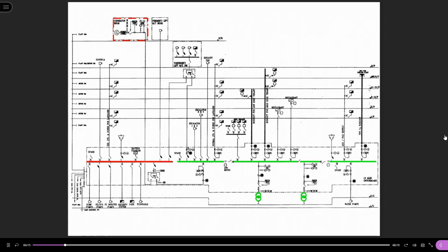So the equipment, the lighting, the small power inside the restaurant, inside the office, inside the shops, they are the tenant load. Okay? And for the rest of the loadings, they are all landlord load. Like the chiller plants, the water pumps, the air conditioning, and also the small power and lighting for the landlord. For the lift lobby, for the toilets, for the entrance lobby, and so on.